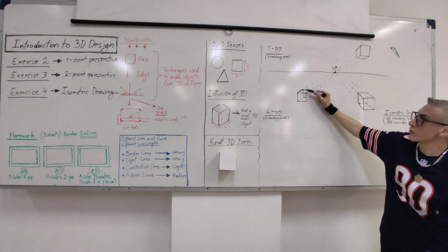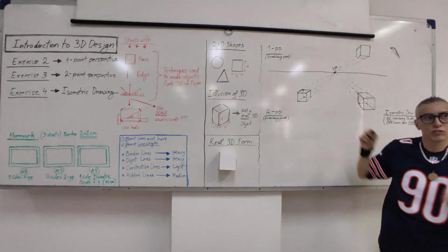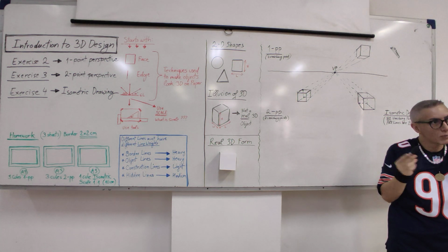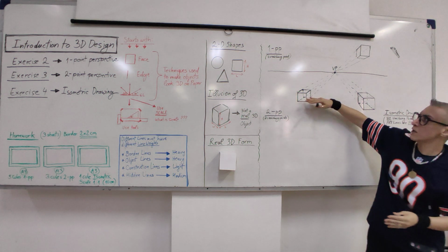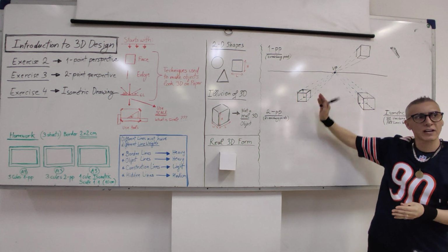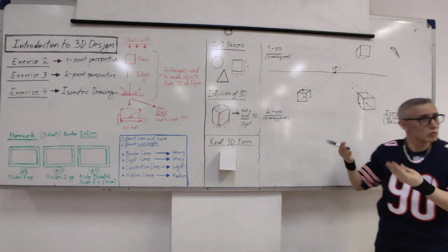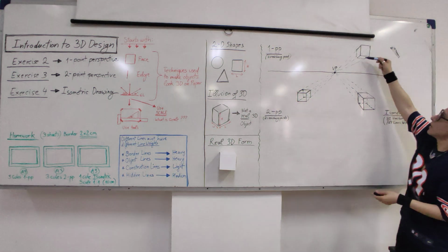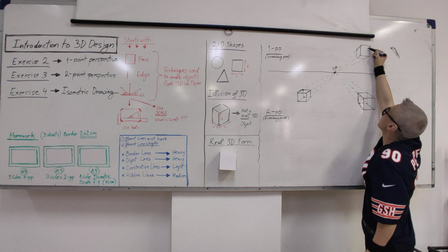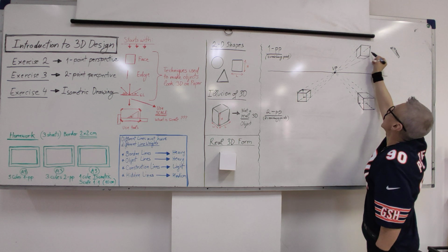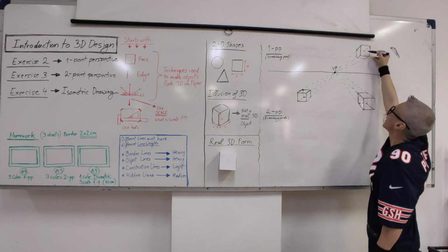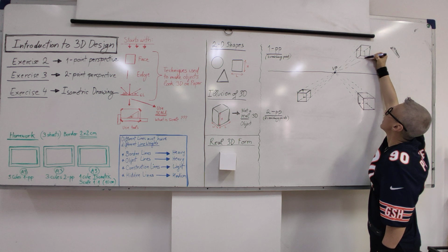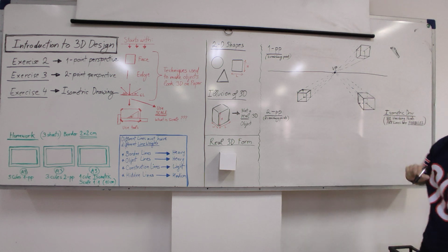Now, if you draw these three lines and they don't touch in a point, it means there is something wrong with the drawing, okay? There is something off. Maybe your line is not parallel, maybe there is something wrong with it, so you need to repeat it. Okay. The same thing here. So here we have this line, and we have this line that needs to be parallel to the others and touch this line, and then this corner down to this corner to touch.